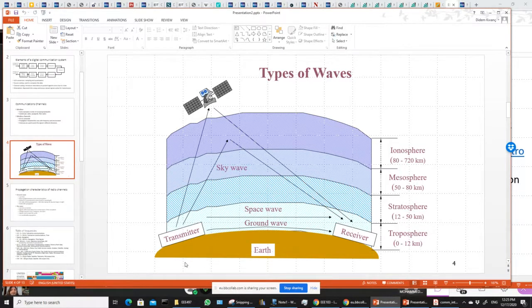There's always something. Why? Because of conductors. Remember about conductors? They won't, because they just conduct away essentially the electromagnetic field. Using the electromagnetic field to communicate, the conductor just conducts it everywhere else, and it doesn't go into the conductor. That's why you have a Gaussian surface, right? So ground waves, though, are the bits of the waves that stick close to the ground. Why? Often they reflect off very low clouds, fog, things like that. And you can think of the ground as a giant conductor. So they kind of go that way because of that.